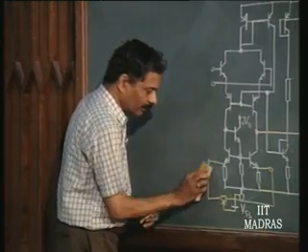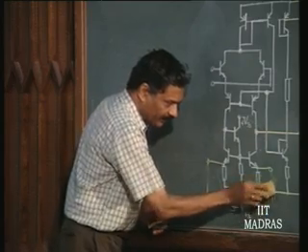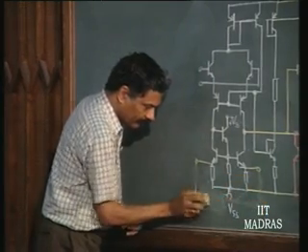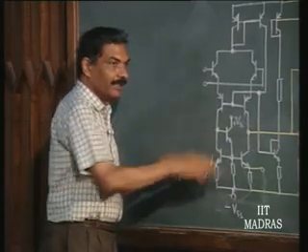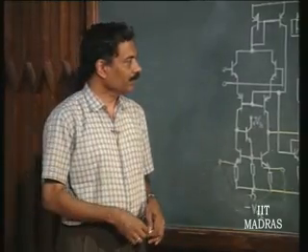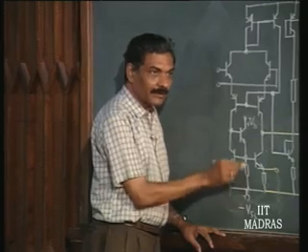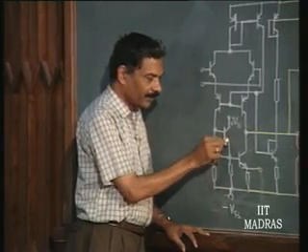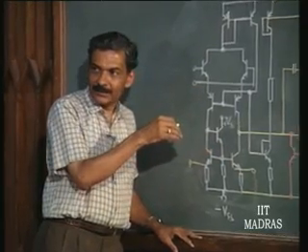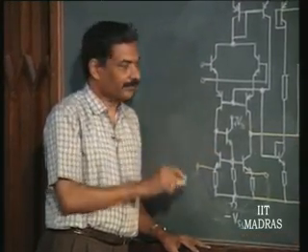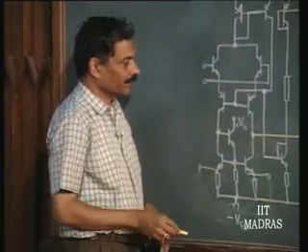So, we will remove this, because this being an outside component, we should not clutter this already complicated circuit with all this. In case of offset compensation, therefore, we need this potentiometer. Now, this is nothing but the bleeding resistance we are talking of, okay, in order to make this transistor operate at sufficiently high current, okay, so as to prevent the beta fall off. Okay. So, this portion is understood thoroughly. This is connected to plus Vs.